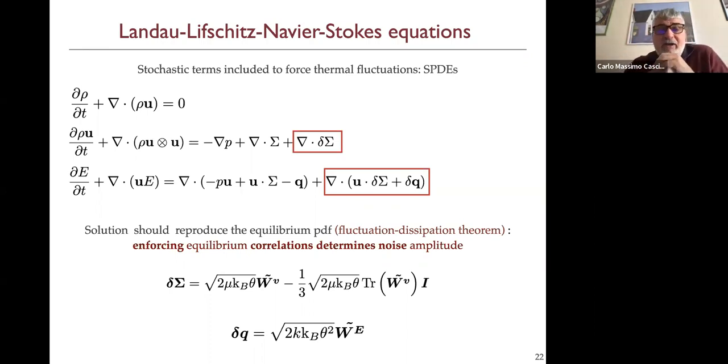So now we have turned our capillary Navier-Stokes equations into equations with a stochastic forcing. They are a sort of generalized Langevin equation, and now we can solve those Langevin equations. In particular, we need special integration techniques, because we need to be sure that the stochastic terms are treated properly, that is, they produce the expected correlations. And once we have done that, we can discretize those equations and implement them on a computer. Let's see what happens in this case.